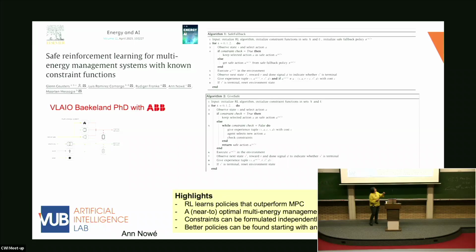So there was on top, and that's called a safe fallback, where if the action that is being proposed is too much out of range of what your traditional control technique that is currently used would propose, it's overruled, and that's just what is happening on top. But then the second version is where every time the RL agent is being overruled, it's also considered to be like a negative reward.